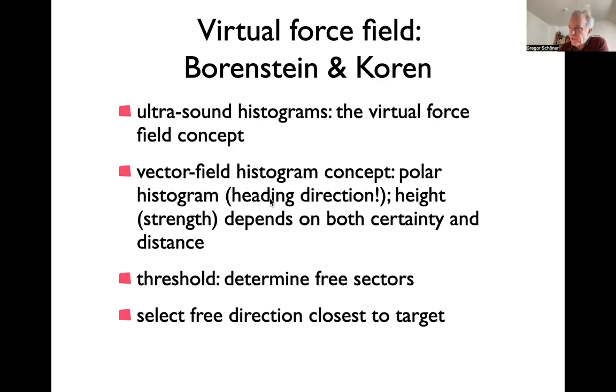And so the vector field histogram concept is sort of a really low-level way of doing the mapping. We, in our first paper with Michael Dose, actually did something related, and this is what I was hinting at, that we were representing obstacles. So we were selecting in a grid of the world's grid points where there would probably be an obstacle and just selecting a subset of those. And so that's sort of related to this vector field histogram concept. So it is about detecting free directions.